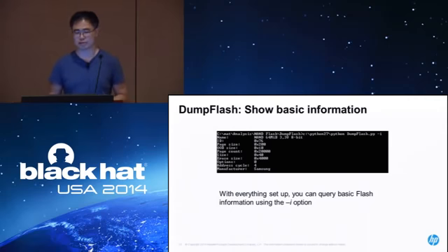For every 0x200 bytes, there are 0x10 bytes of OOB data inserted. So it's not a flat image, but every page has OOB data. Those 3 bytes are for ECC, and the 6th byte is for the bad block marker.